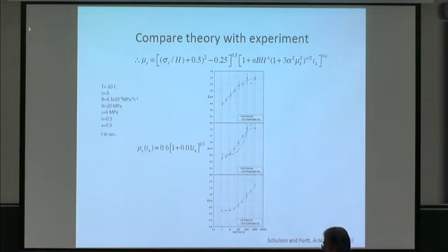With this very simple relationship, the coefficient of static friction as a function of holding time at -10, at a particular intermediate velocity, is given by this dotted line. So there's the dotted line coming out from that model. The measurements are the points you see here. And there's a modest agreement, not perfect for sure. The model seems to underestimate the coefficient of friction a little bit, maybe by 10% or so.